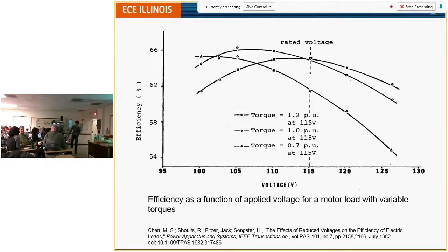Yes, Professor. The other nice follow-up is to tie this into power electronics, right? It could be that the efficiency of your power converter could be marginally different between 114 volts and 126 or something like that, right? And then essentially, it's a step down. If you have to do a little less step down, sometimes it's very dependent on the power converter quality, but I can see there being a small percentage change in efficiency, perhaps.